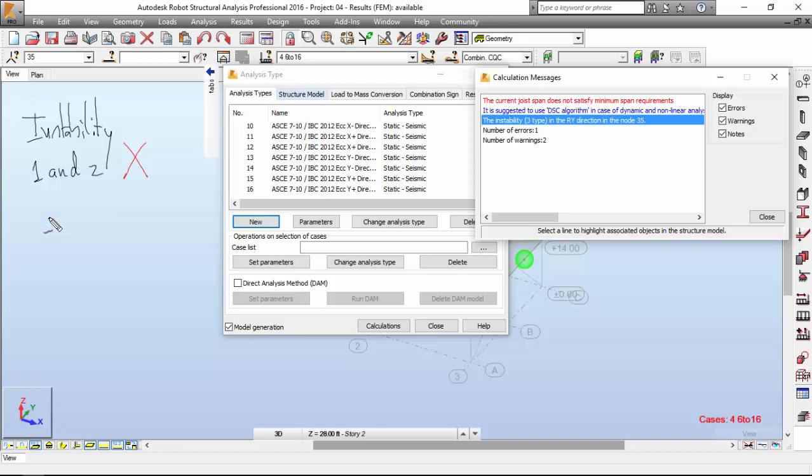This is the case when you have a bar with 3 hinges. Okay, and something like this is going to happen. The bar is going to this position to find a new point of equilibrium, and you may not use this. Okay, so when you have instability of type 1 and 2, something is really wrong in your structure.